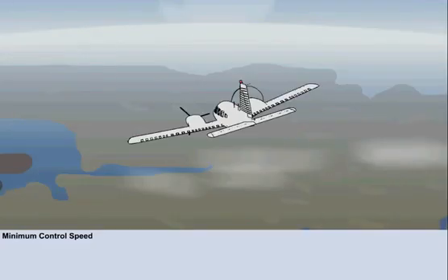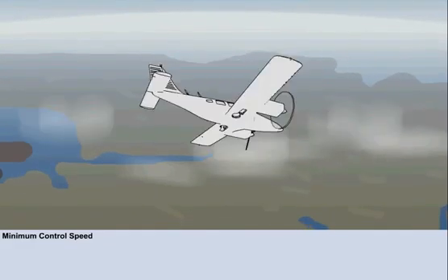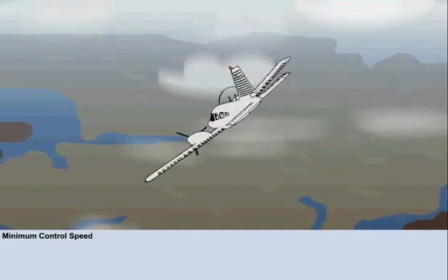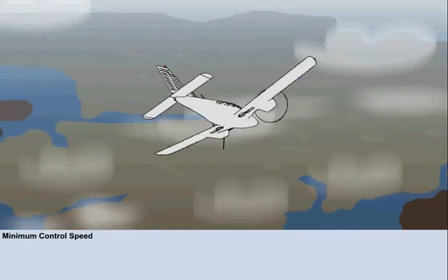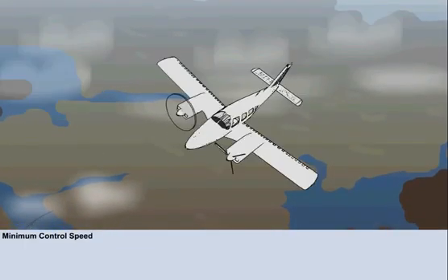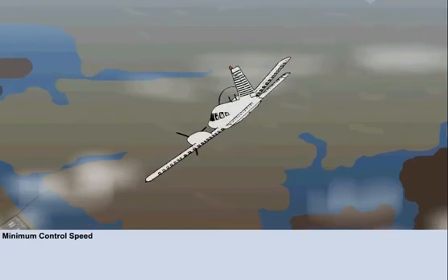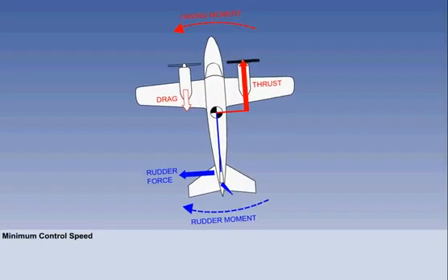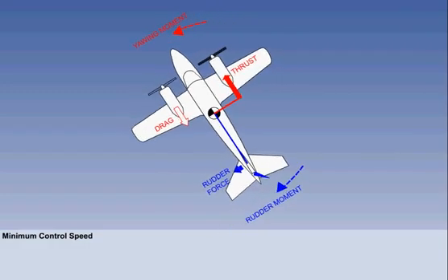This uncontrollable yaw, in this case to the left, will cause the aircraft to roll uncontrollably, also to the left, owing to the greater lift on the starboard wing whilst yawing left. The aircraft will enter a spiral dive to the left, which at the low speed would be impossible to stop with flight controls alone. If this were to happen close to the ground, the result would be disastrous. In these extreme circumstances, the only way to regain control would be to minimize thrust on the live engine or engines, to remove the yawing moment and permit a controlled forced landing.